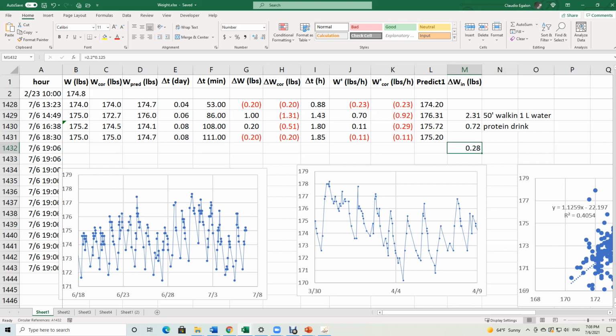Let me stop sharing so you can see better. My LED is lighting up, right? If I disconnect my resistor, the LED turns off. See that? I connect back my resistor, the LED turns on. What does it mean? It means that elements that are connected in series, once they fail, it affects the other elements. If this resistor fails, it's as though it became disconnected from the circuit. And because it failed, I'm going to think that my LED failed as well, when in reality, it was the resistor that failed.